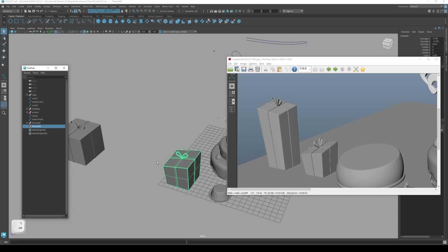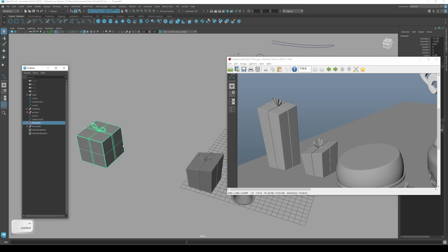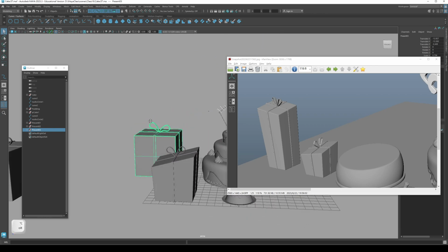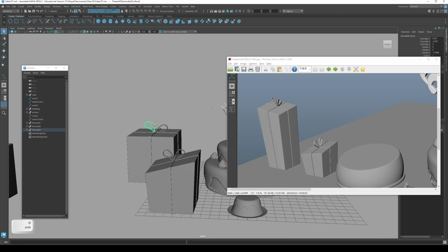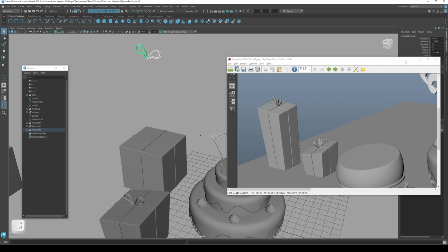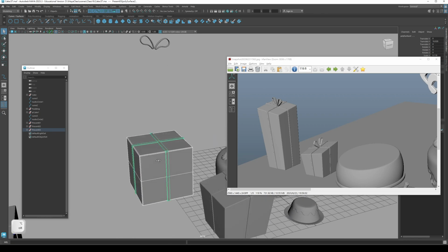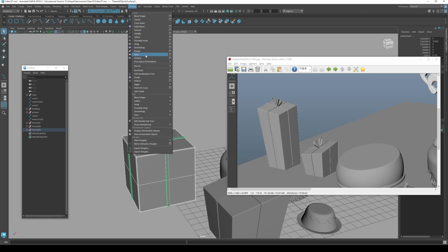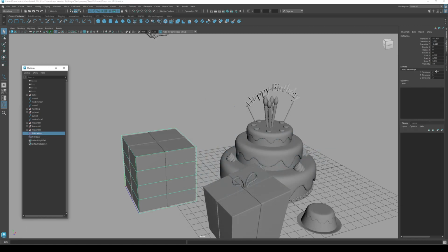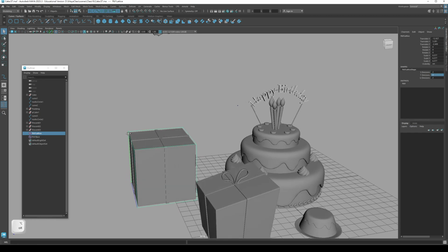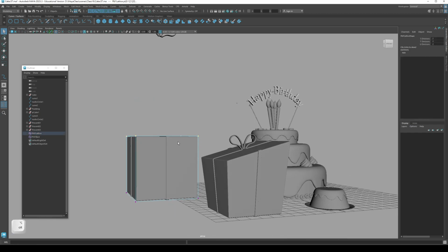No, present 2. And then let's duplicate present 1 again, move it to here. And yeah, you know what will happen. Slide this belt up a little bit. Move that. And then select both the belt and the cube, and then go to deform lattice, set the division 2 by 2 by 2, and this time make it taller.